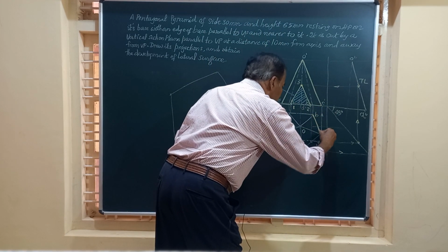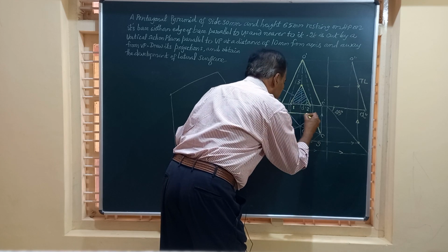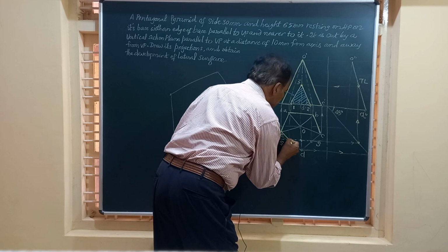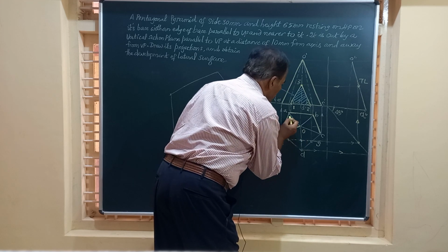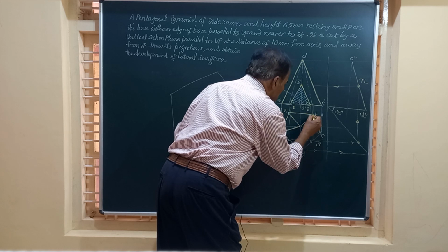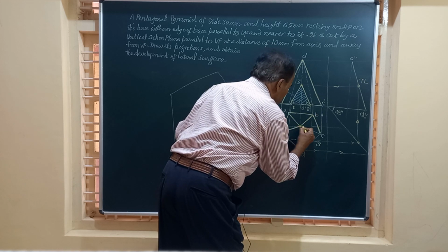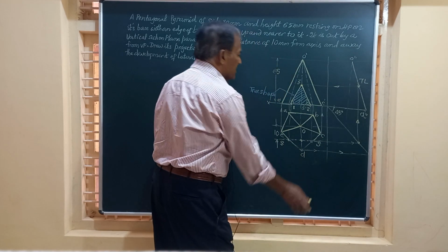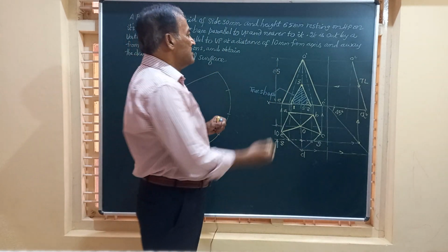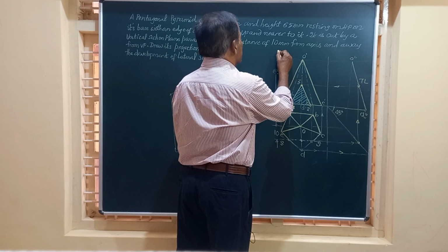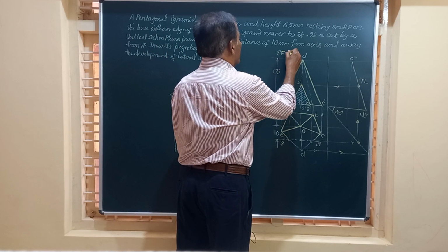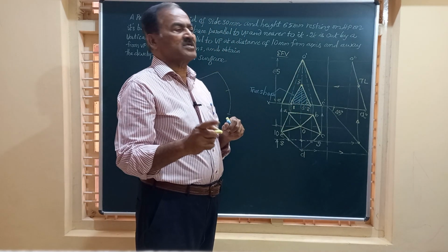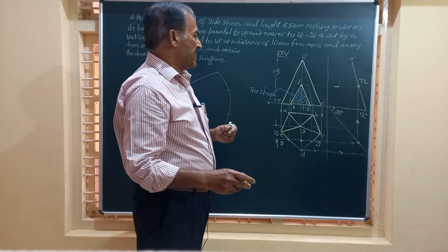So I will represent the remaining part of that by visible lines. So till here it is retained. This line, edges OE, OA, OB, and OC are also retained along with this shorter portion. This bottom portion of the solid is removed. And friends, we call this the sectional front view, SFV. And this hatched portion will give you the true shape of the section, and it is going to be a triangle.